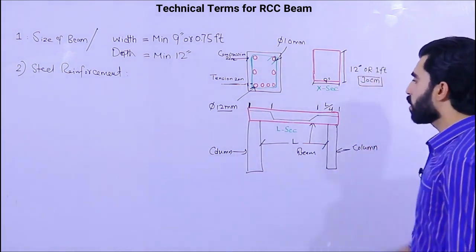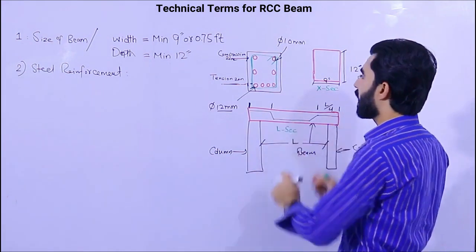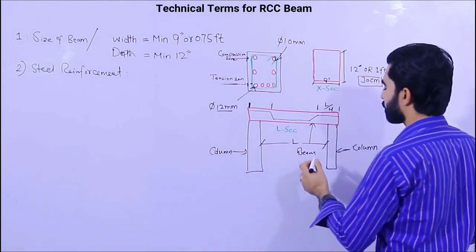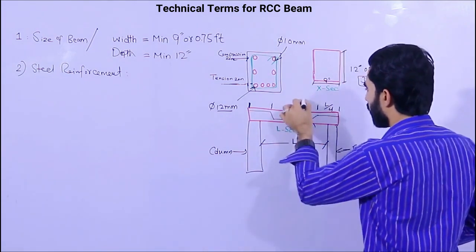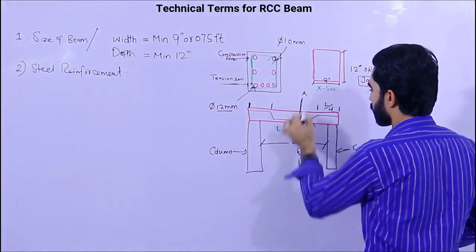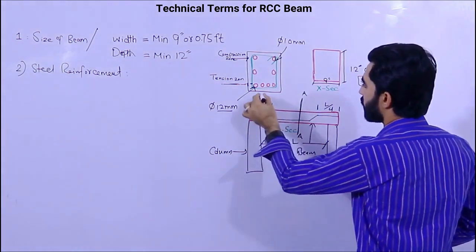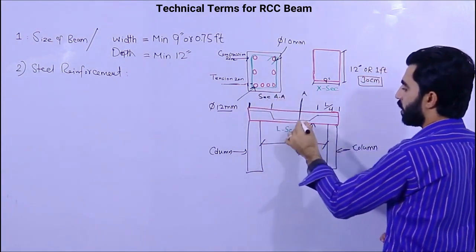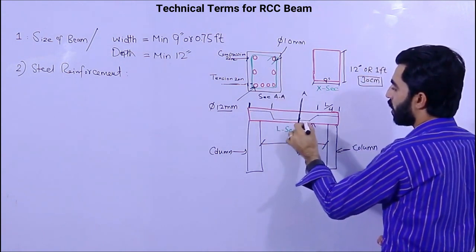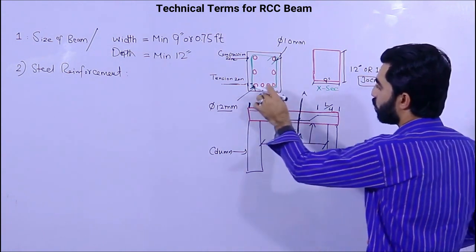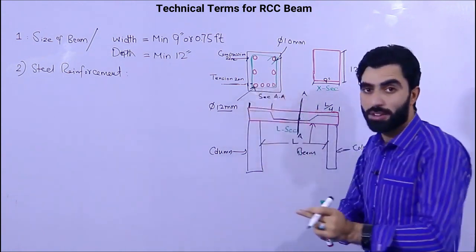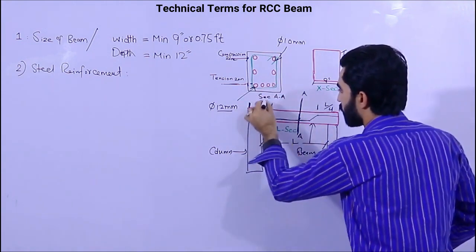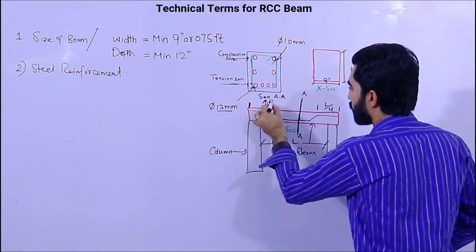Okay. Now guys, when we bend the bar like this, for example, here we have 2 sections. Let me show you the AA section. So this is section AA, because at this section the steel rods are at the bottom. So we will use all the steel rods at the bottom here, 4 steel rods. But when we come to this point, this is the BB section.